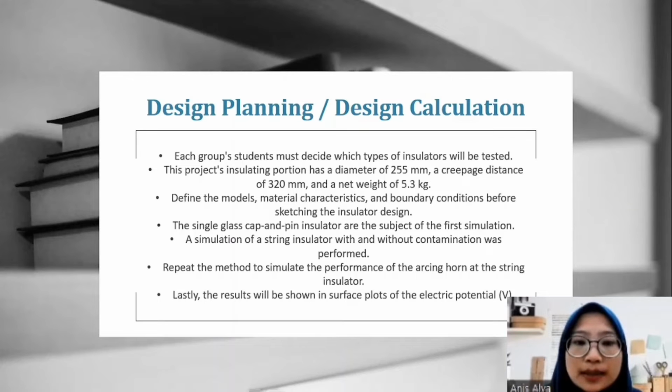Each group's students must decide which types of insulators will be tested. This project's insulating portion has a diameter of 255 mm, a creepage distance of 220 mm, and a net weight of 5.3 kg. Define the model's material characteristic and boundary conditions before sketching the insulator design.